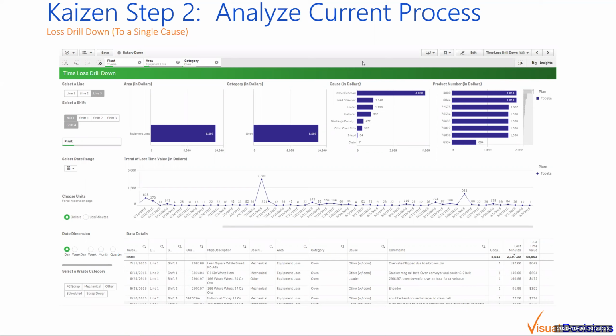And so these big spikes were occurring. Well, we were able to identify that cause, and then we could put a PM program in place to, on an off shift or on an off day, have somebody inspect those pins, see where they were getting fatigue, replace them on a more regular basis, and we eliminated this entire source of downtime and raised the OEE of the equipment by a significant amount just through this one change.